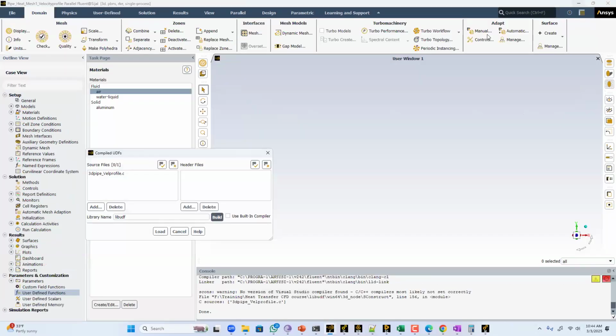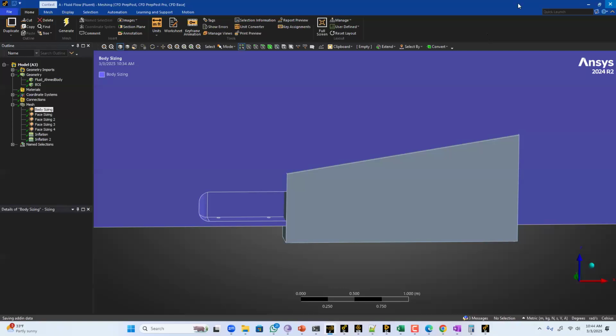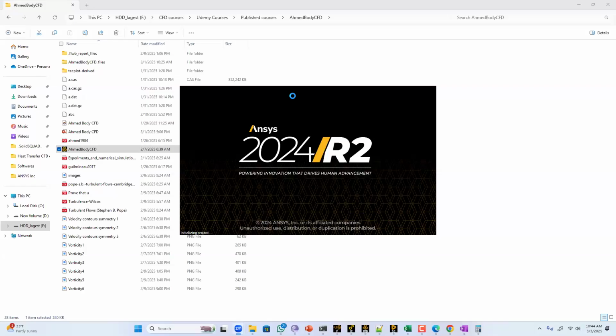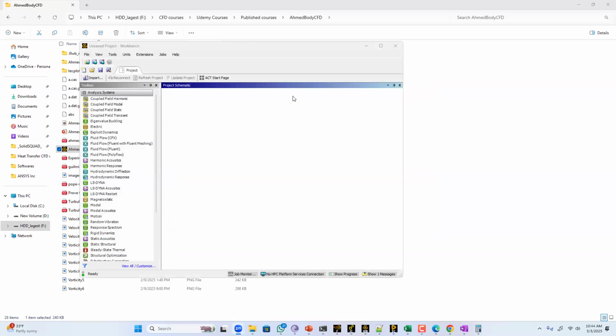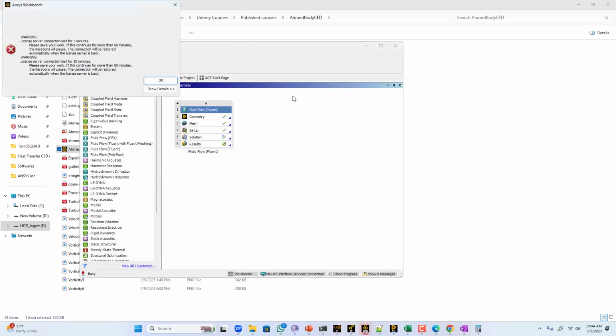Sir, why did you take the length scale, or the eddy length scale, from the wall, not from the domain? No, I didn't take it from the wall, because if I go with the wall size, that will require a very fine mesh. So in these DES type methods, we are going only for the part that is in the wake region, in the pressure drag, the free shear flow. Those are bigger eddies than the eddies we have in the boundary layer. The eddies play the most important part in the wake region, not over there.